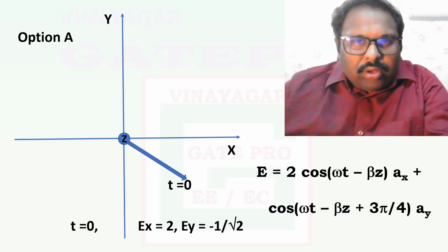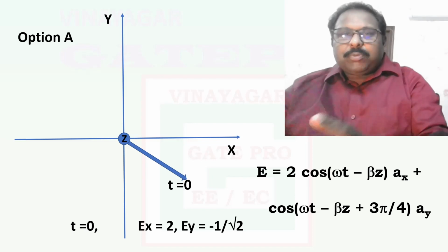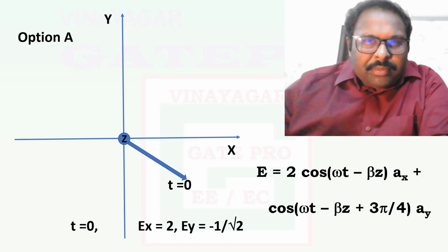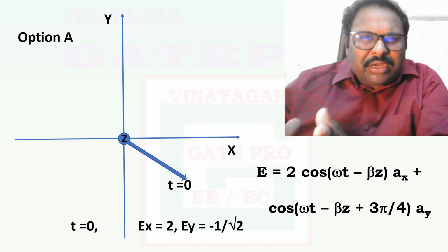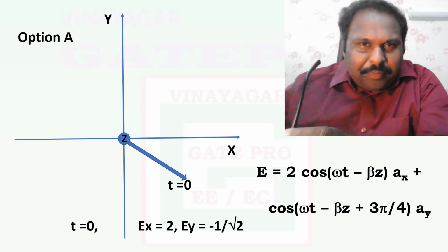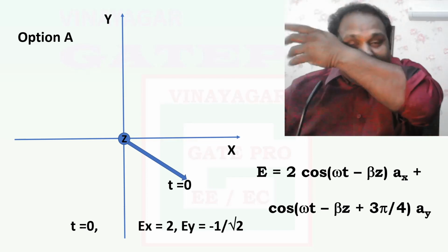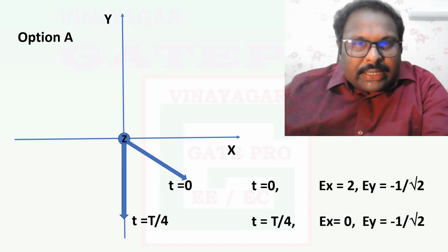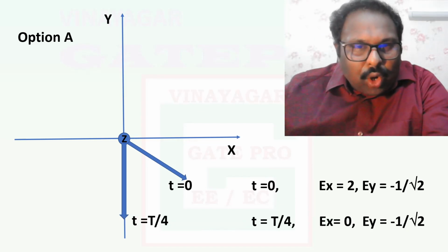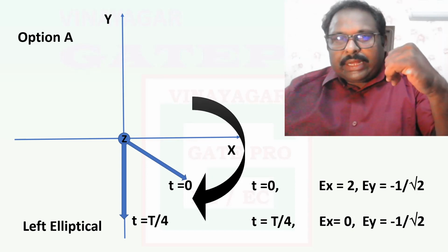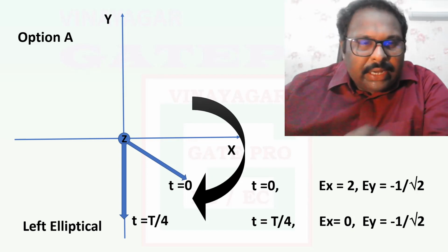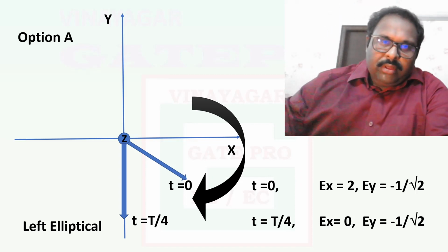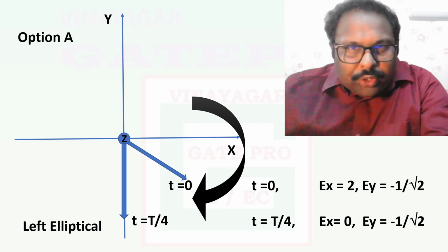There's no other alternative. You can't do stupid things like if the angle is positive, subtract this, do that. You can't check leading, lagging. These are all last-moment guidelines which will never help you in the right direction. So I want the student to clearly cross check tracing at different times. And if you trace it, the trace is moving clockwise with the thumb out of the screen, and it's clearly left elliptical. This is a strategy you should be applying. This is a way of giving a solution.